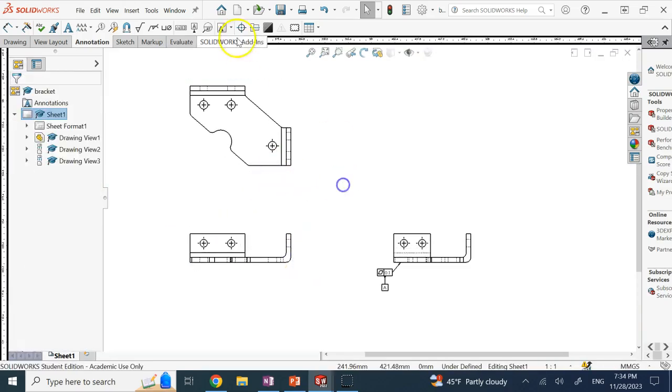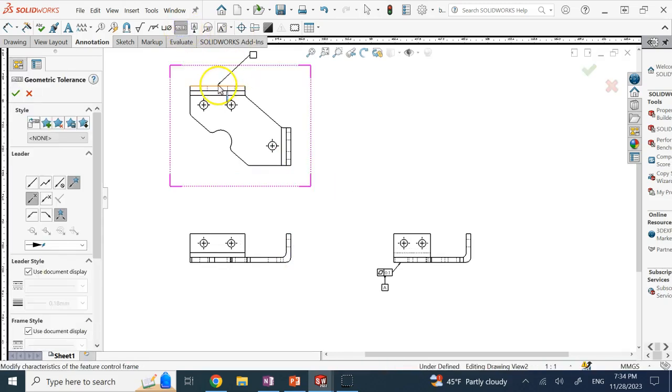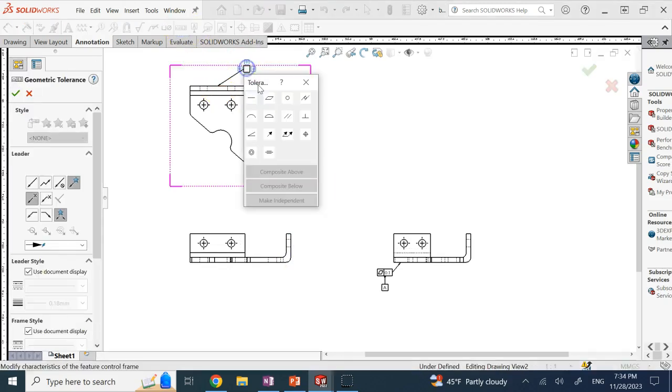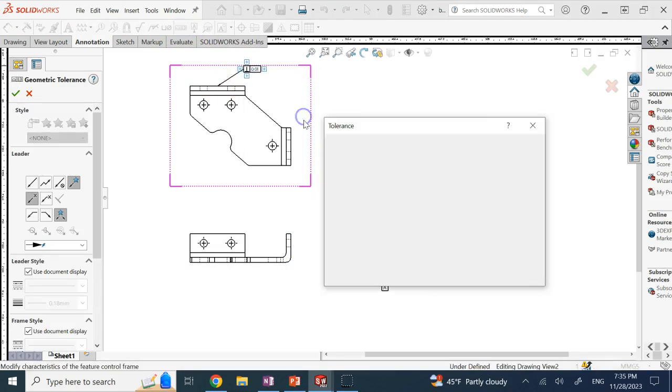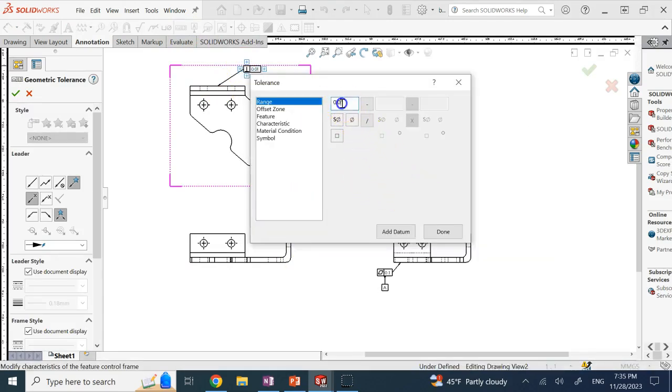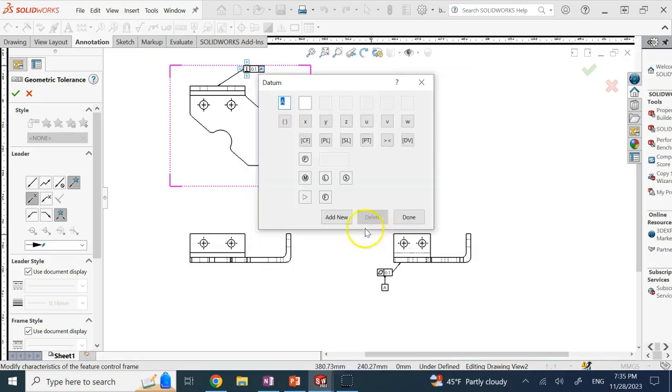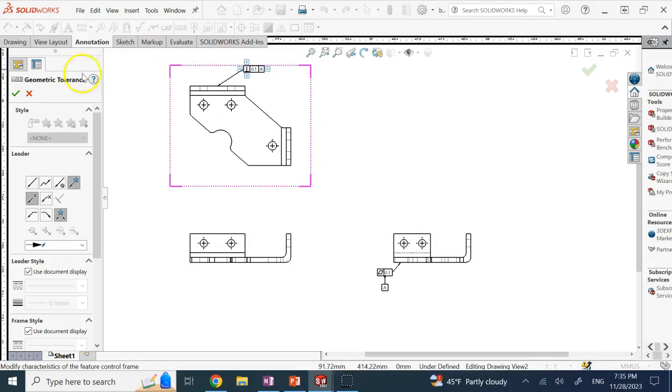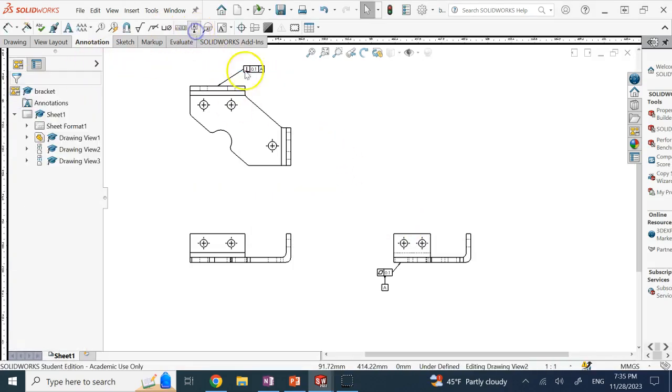So now we go with this surface. As I said, this guy is B. So we are going to make it perpendicular to A, and again I use the same perpendicularity tolerance that I used for flatness, and this is with respect to A, of course. And as I said, I'm going to call this guy B.